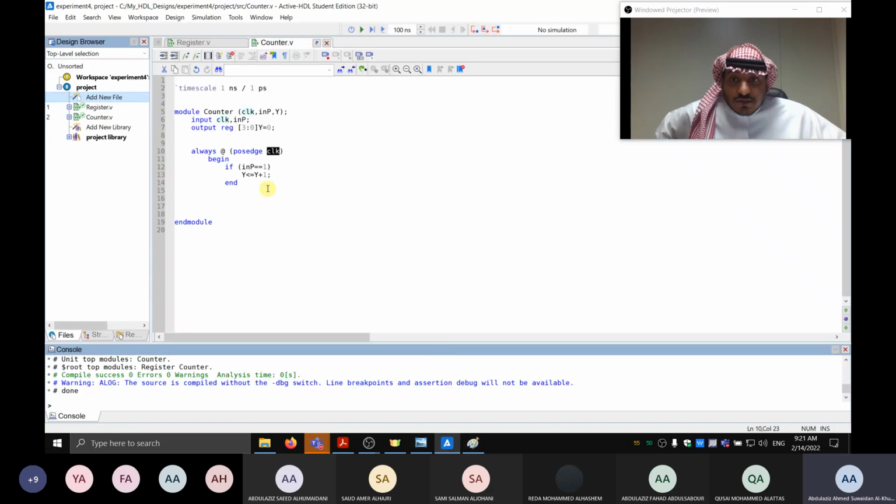So you see in the code, always at the positive edge of the clock, you press a button, it will count up. Then going to the next positive edge, it will check: oh, you're still pressing the button, I will count up. And you're still pressing the button, I'm counting. So you see the system, pressing the button, it counts many times. So how to fix it? That's the major issue.